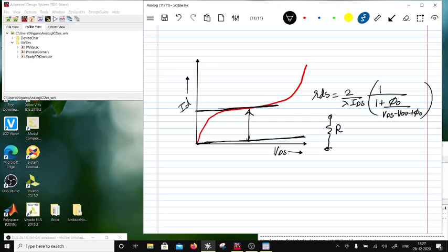So to build up the same current, I would have to go a very long way before I build up the same current, correct? In that case, the voltage across here will be IR, and that would take away the entire supply voltage VDD. So then you will be left with nothing across this device, which is going to act as a gain